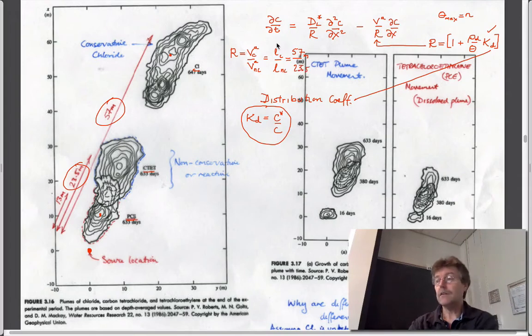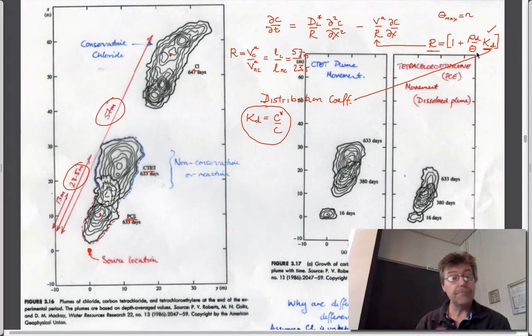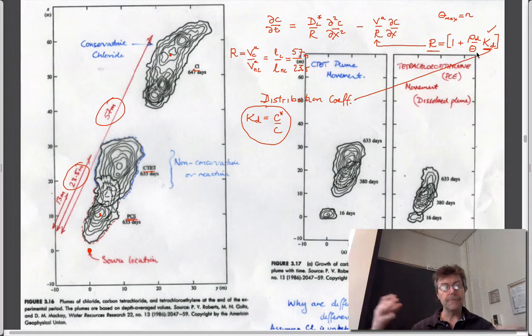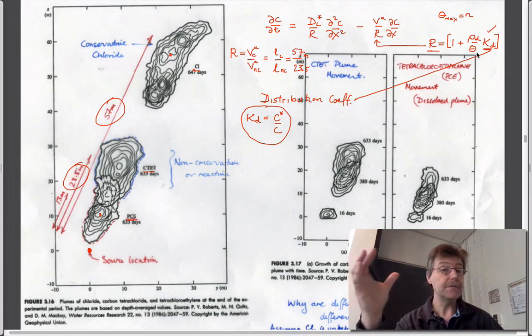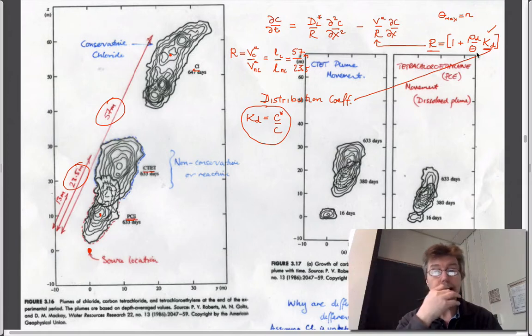And so that's kind of a potted view of what we talked about last time. We might be interested, so certainly we can get this retardation coefficient. If we get the retardation coefficient and we know what these other parameters are, we can get a distribution coefficient from field data. That probably is the most accurate because it satisfies the fact that it's sampled a big portion of the aquifer. It's traveled a representative distance downstream, and it's under gradients which are relevant at field behavior. And so it might be the best way we can get it.